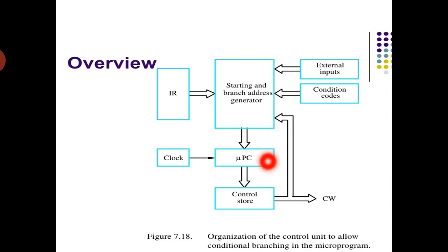Here in this control unit or control store, the microprogram counter is incremented every time a new micro instruction is fetched from the microprogram memory, except for 3 conditions where the microprogram counter will not be incremented.